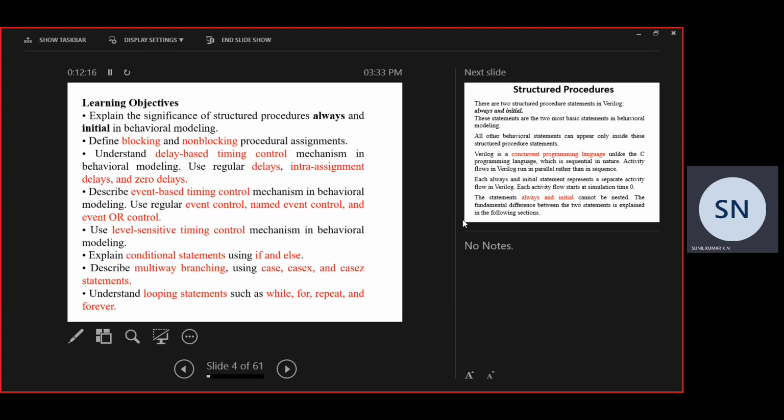So whenever this statement gets executed, then only these two statements will execute. Even though we are giving the same delay #10 followed by a series of statements, all the statements will not execute together, even though it is concurrent. With a blocking assignment operator, the next statement executes only after this one. So even though all these statements happen at 10 nanoseconds, the first statement to execute is reset, the next is S, and the next is R.